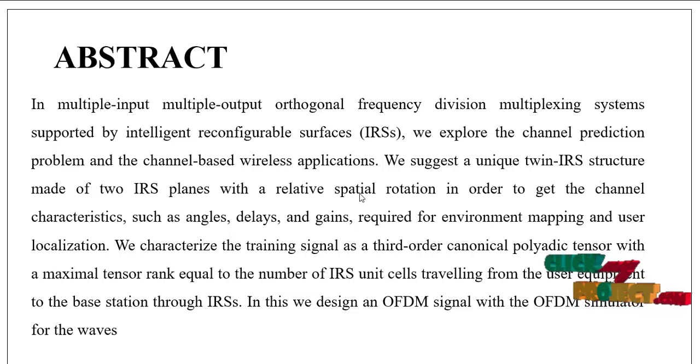For environment mapping and user location, we characterize the training signal as a third-order canonical polyadic tensor with the maximal tensor rank equal to the number of IRS unit cells traveling from the user equipment to the base station through the IRS. In this design, we design an OFDM signal with the OFDM simulator for the waves.